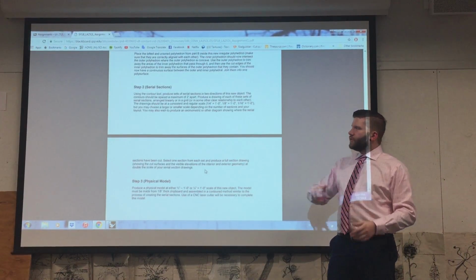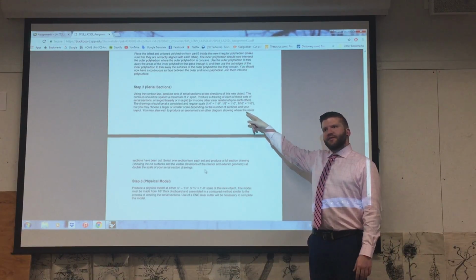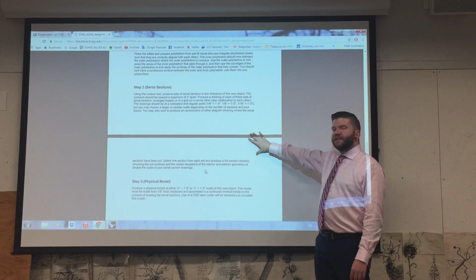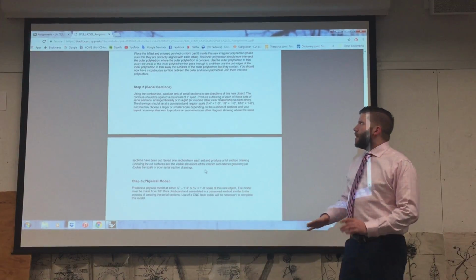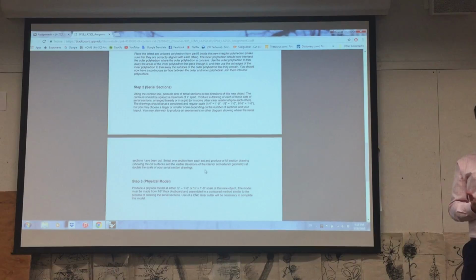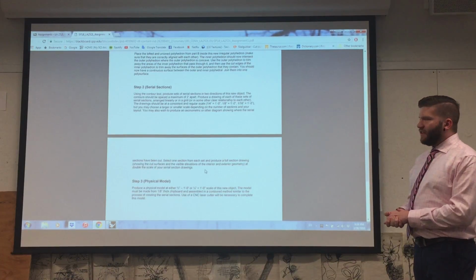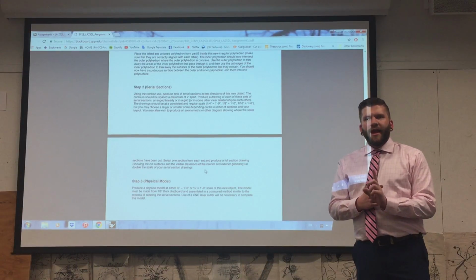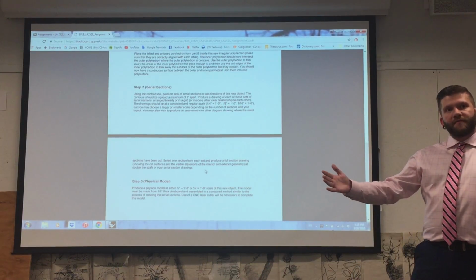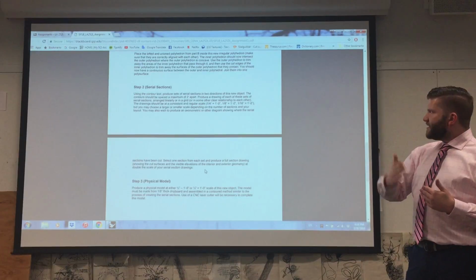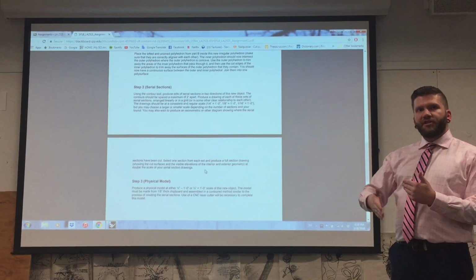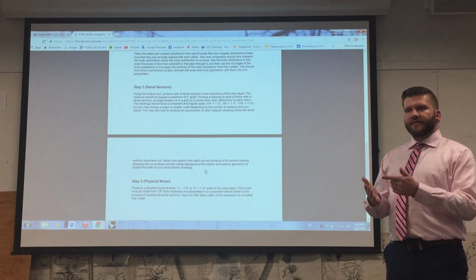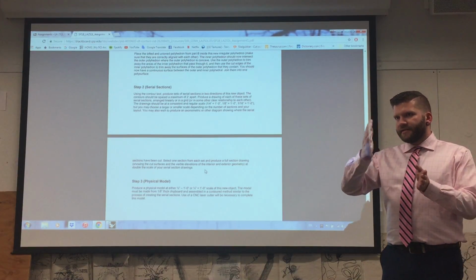In terms of deliverables, this serial section step will be what you end up printing on paper. And it's very simple to do. I'm going to use the contour tool in the X, in the Y, and in the Z. And over the course of this object, I'm going to have a section cut every 2 feet. So that in the X, section cut, section cut, section cut, section cut.